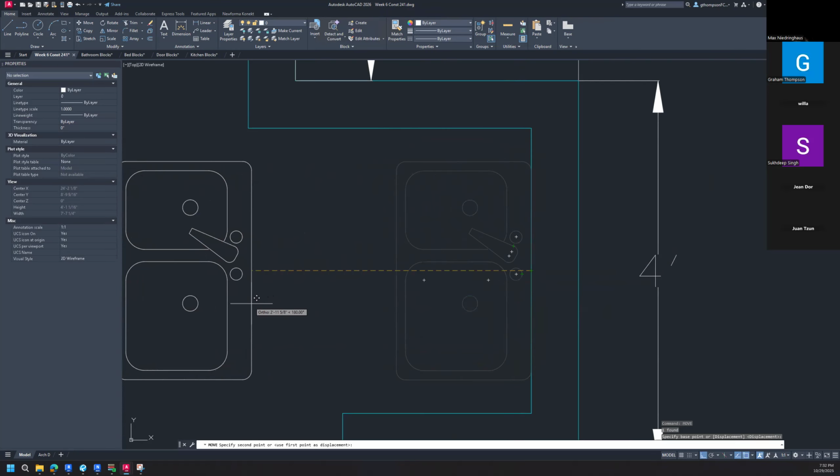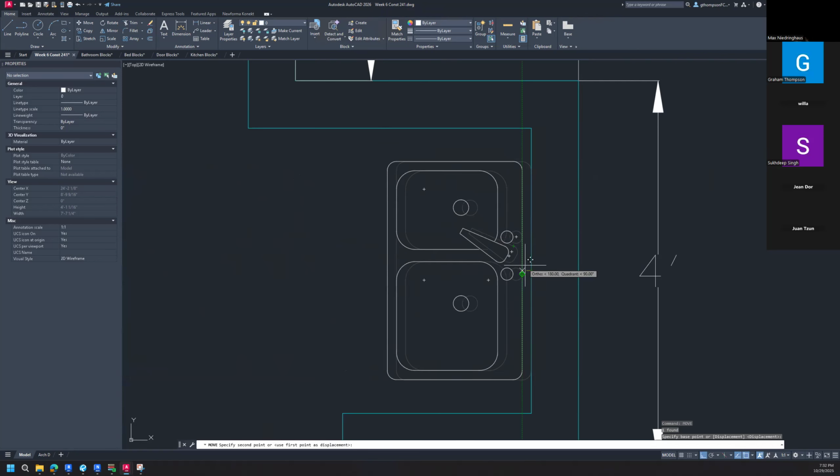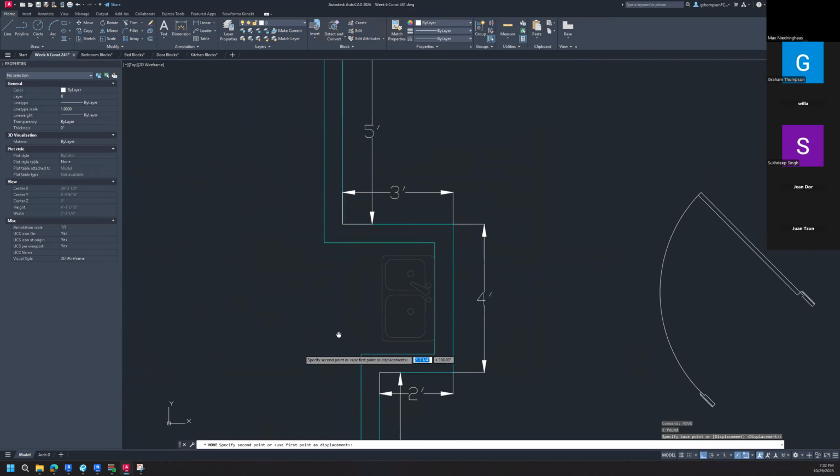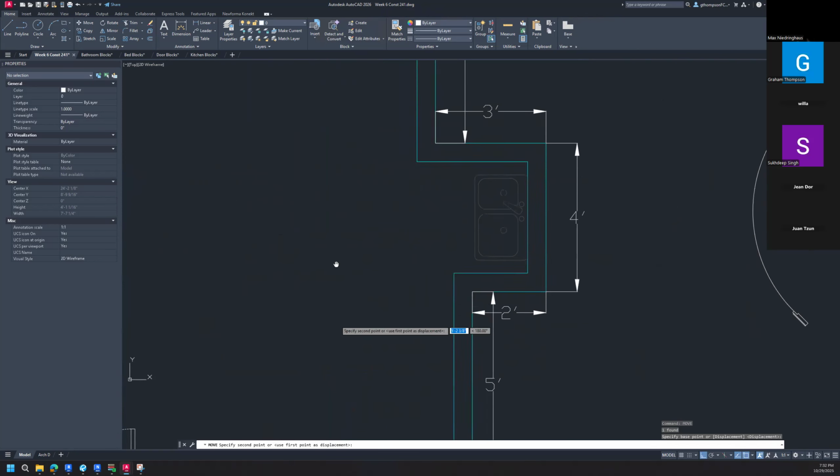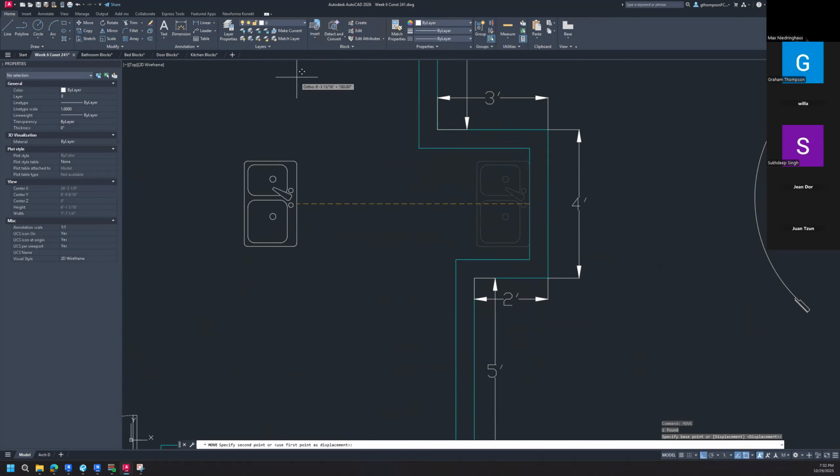And I know that it's really easy. I can't make a mistake of, am I going sideways at all? Am I still centered? Right? That ortho keeps me, I can even move my mouse down here, up here. It doesn't matter. All that matters is I'm ortho, I'm away from the wall, and I want to move it 2 inches. So I can type in 2 inches, hit enter, and now I've got that sink 2 inches away. And maybe that's perfect for that area.